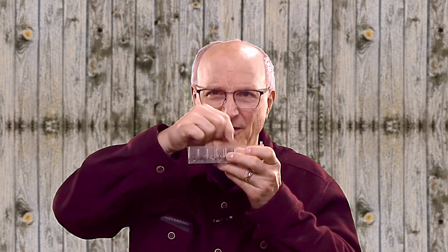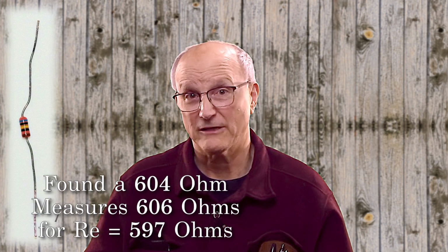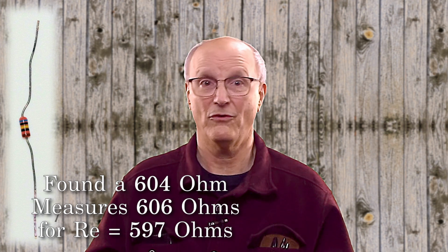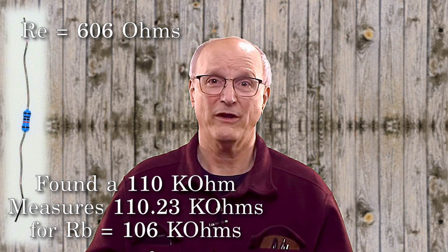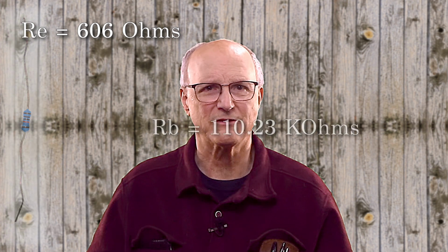To put this on the bench, I began by randomly choosing a 2N3904 transistor out of my collection. Then, looking at my junk box, the closest I got to the calculated resistor values was a 604 ohm resistor, which actually measures 606 ohms, to use for the 597 ohm emitter resistor, and a 110 k ohm resistor, which actually measures 110.23 k ohms, to use for the 106 k ohm base resistor.